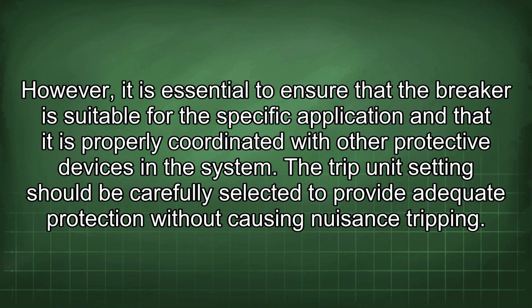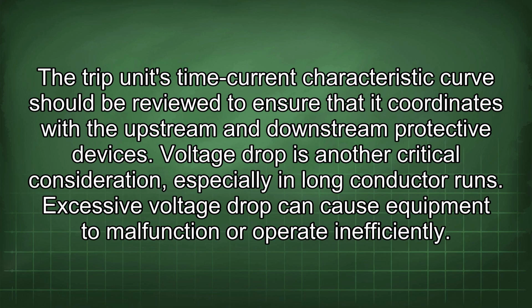However, it is essential to ensure that the breaker is suitable for the specific application and that it is properly coordinated with other protective devices in the system. The trip unit setting should be carefully selected to provide adequate protection without causing nuisance tripping. The trip unit's time current characteristic curve should be reviewed to ensure that it coordinates with the upstream and downstream protective devices.